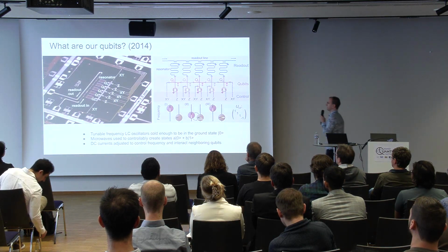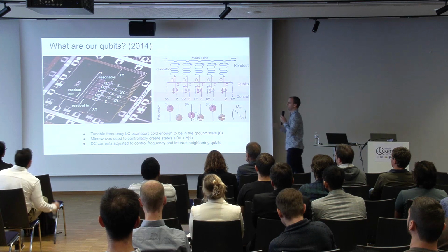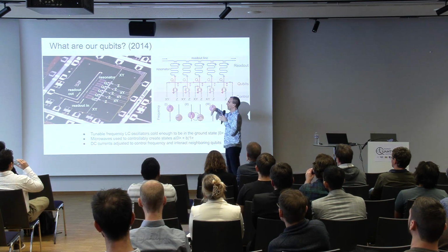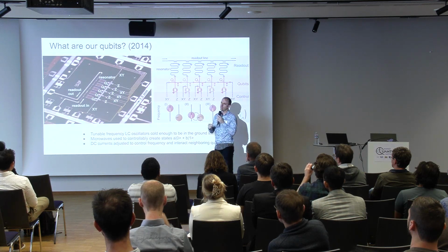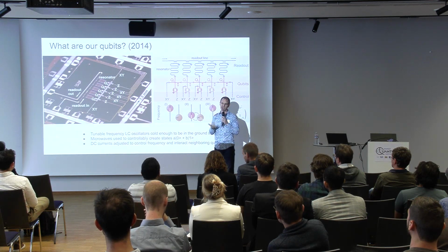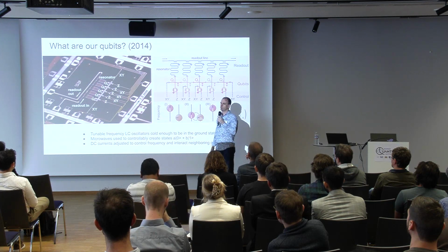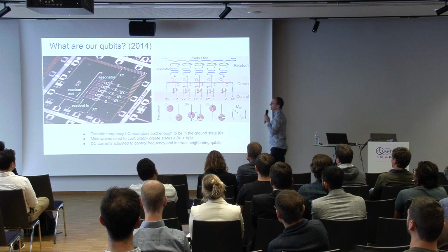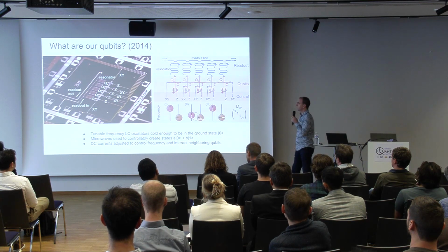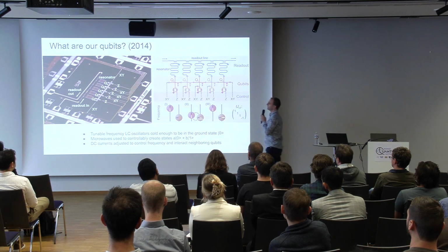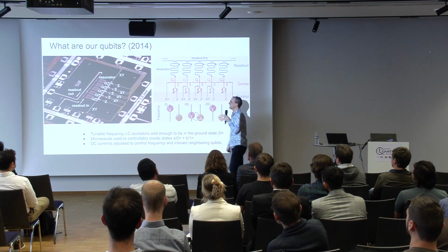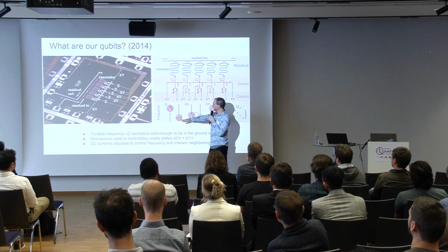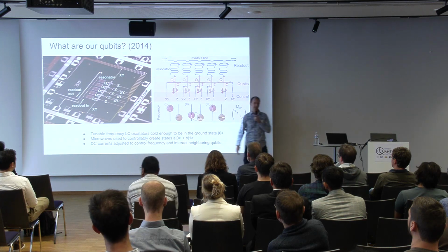So more specifically, we have an LC oscillator. So it's an oscillator with a fundamental mode, a first excited mode, and more excited modes. It's not technically a qubit, it's a multi-level system. You could in principle use it as a qubit, we don't. We focus on the lowest 2 levels. Any excitation above the first excited state is an error called leakage. These qubits have a tunable frequency, and in essence, we can tune the frequency such that we're either interacting or not interacting and do gates.